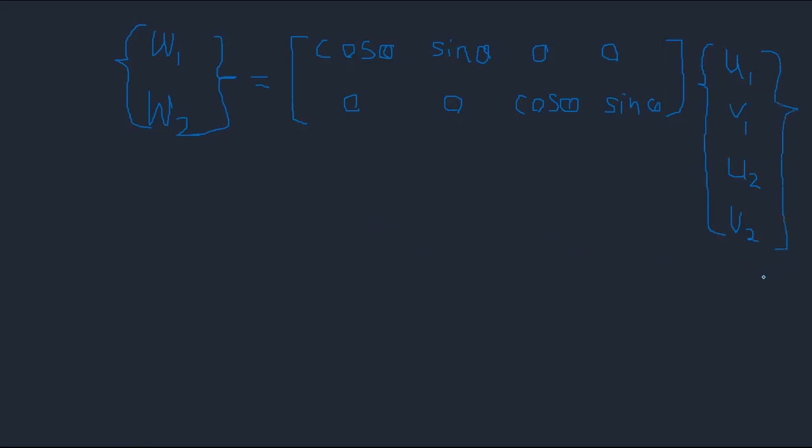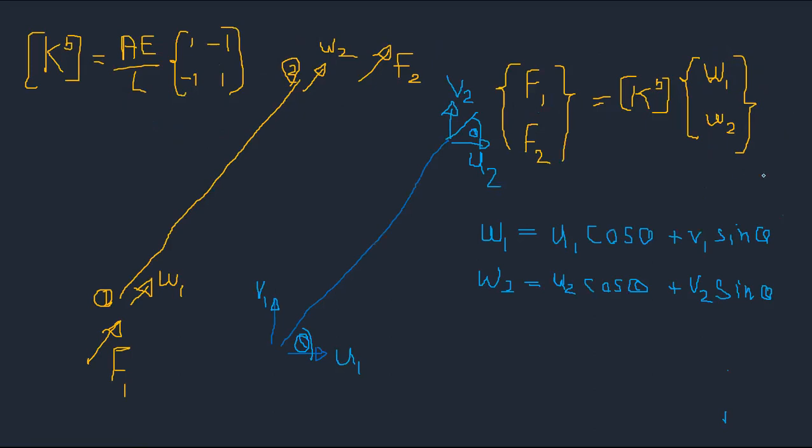So this is very important when this is the node FEM output displacement. If you have the FEM output, you can directly convert this into local displacement, right? At the nodes along the longitudinal axis, right? If you know that, you determine this, right? So you know this one as well, okay? So then you can determine the member force. This is for the element, right? The local coordinate system, element coordinate system. So defined along its longitudinal axis, you can easily determine the tension or compression.